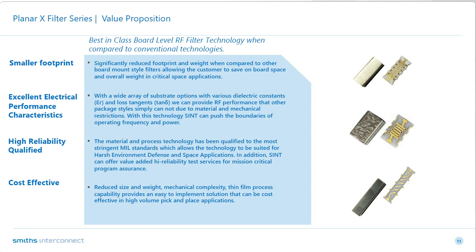When getting into frequencies even higher than the ones we're focusing on in this webinar, quartz with a dielectric constant of around 3.8 will be essential. In contrast, when dealing with lower frequencies such as C-band, a type of titanate may prove to be the best choice with a dielectric constant around 38. There are even some substrates with dielectric constants above 100, but these materials generally have inferior loss tangents, which contribute to higher losses in circuits.